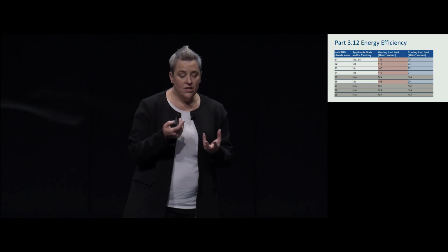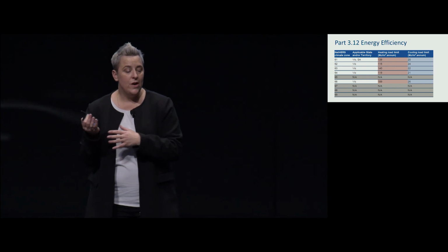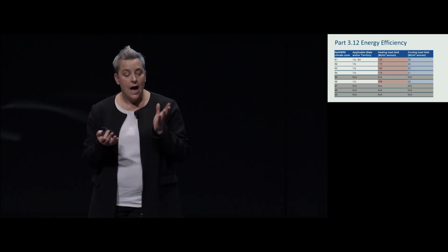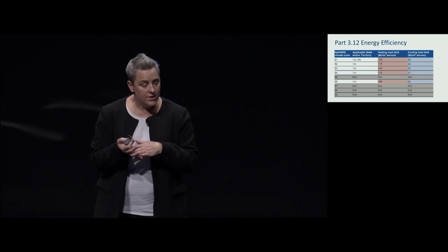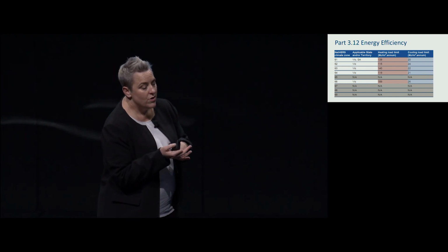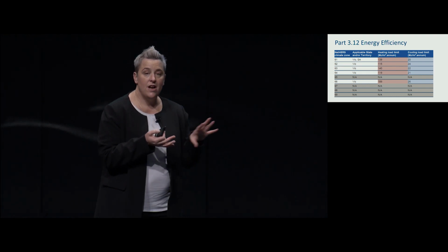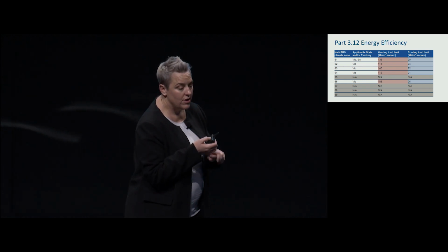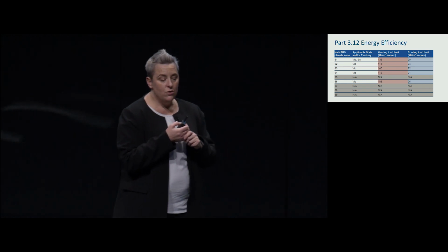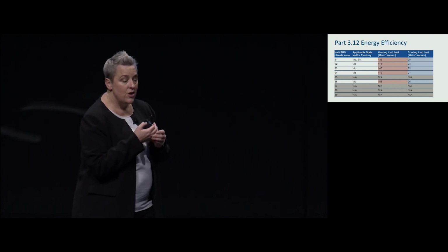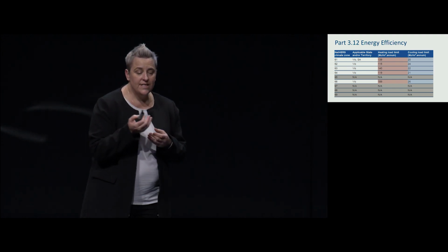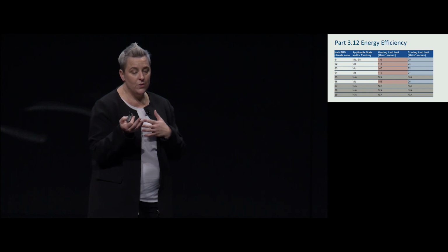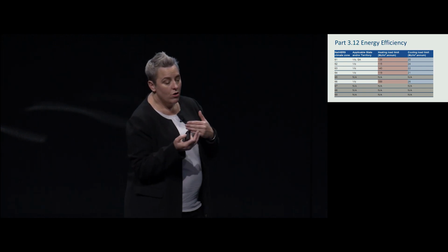In 2019, the NatHERS compliance pathway now requires you to also meet separate heating and cooling load limits that correspond with the star rating specified in the ABCB standard for the NatHERS heating and cooling load limits. On the screen, you'll see an excerpt from the table from that standard, and that applies to a Class 1 building with concrete slab on ground construction.